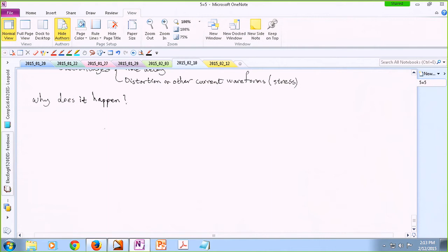Okay, if you look at a diode, a PN junction that is forward biased, a structure like this, you're going to see that you have a bunch of electrons accumulated here and a bunch of positive charge carriers, holes basically, accumulated here. All right. So this is when the diode is forward biased.